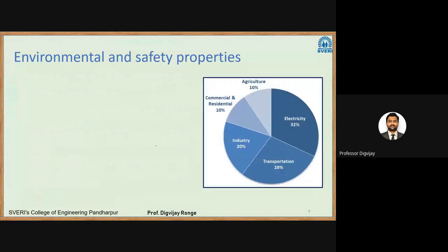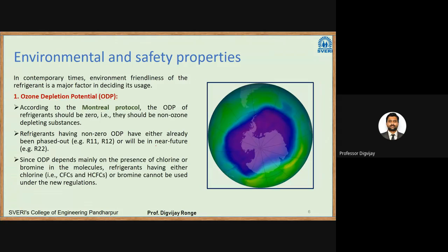So we'll see about these greenhouse gases and ozone depletion potential. Chlorine has the highest ozone depletion potential. So other refrigerants will be compared with this chlorine, that is CFCs, and they will decide what is the ozone depletion potential of the refrigerant. Okay. So for a base, they are using CFC, chlorofluorocarbon. They first calculate its ozone depletion potential. Like, suppose they take 1 kg of CFC, and they observe how much amount of ozone is being destroyed. So that will be its ozone depletion potential.